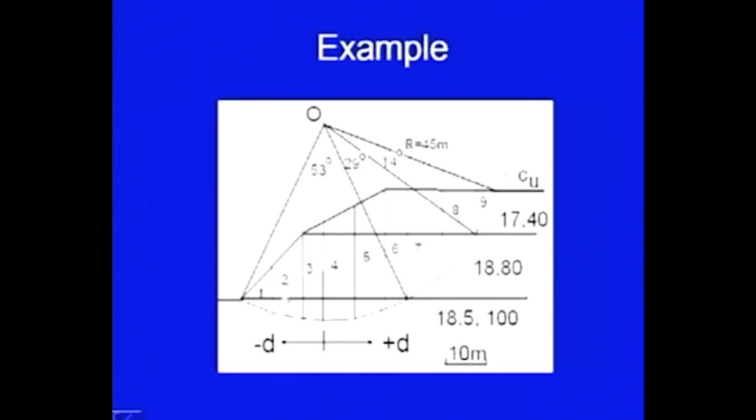Why am I taking different areas? The reason is, here you have the unit weight 18 and here the unit weight is different. So, you have to take A1 gamma 1, A1 into perpendicular distance 1. So, A1 into 1 into gamma 1, and for this slice it will be A2 gamma 2 into 1. Similarly, for slice number 2, A2 will be this much area. A1, this is the area A1 into its unit weight plus this area A2 into this unit weight.